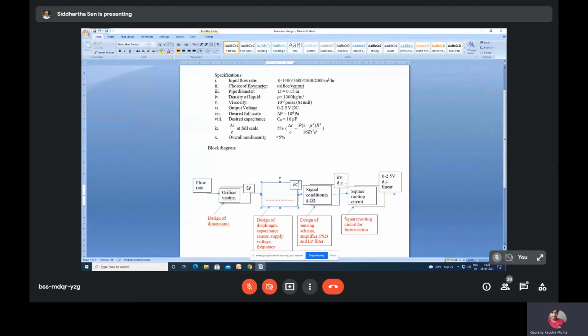So we'll have to start this one, and definitely Bentley's book or any measurement books would be useful. And also, as I told, if you are using an analog multiplier, what analog multiplier you are using and what is its circuit configuration, you have to look into its data sheet and connect it accordingly.